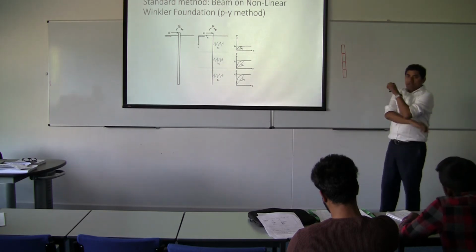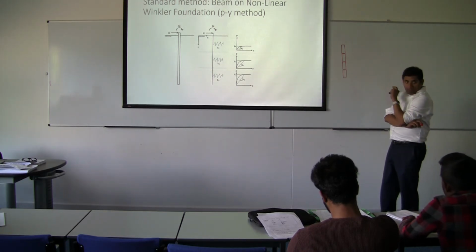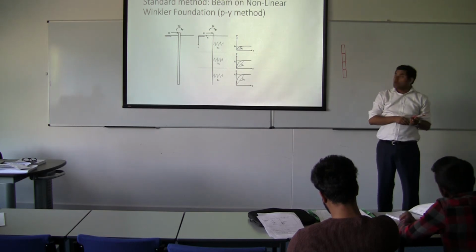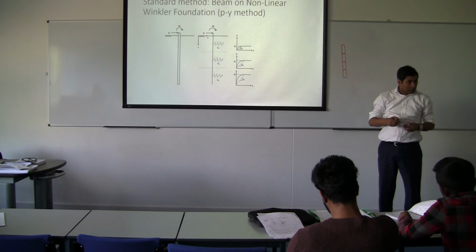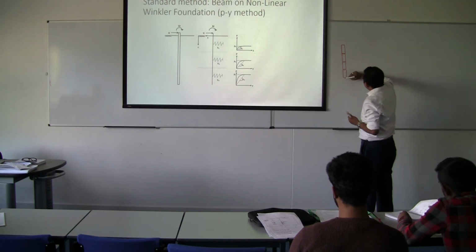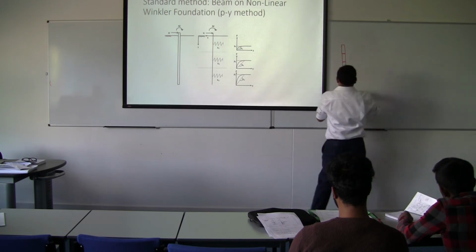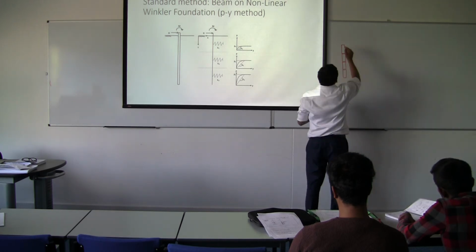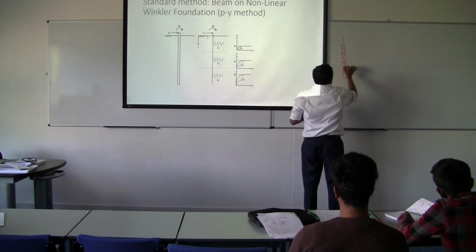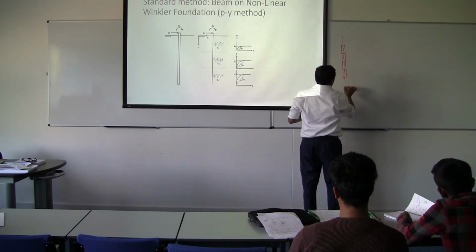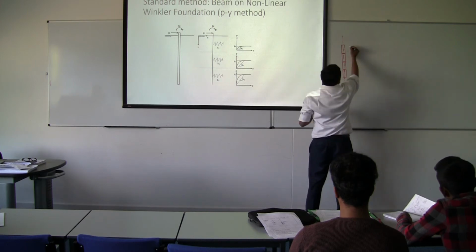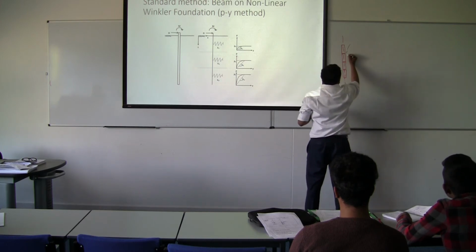Okay? Right? Now, when you apply any lateral load at the top, the pile would deflect, won't it? So as the pile deflects, let's assume a shape of deflection. That's the center line. So it will be higher at the top. As you go down, it would reduce.